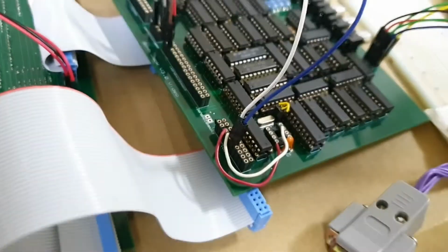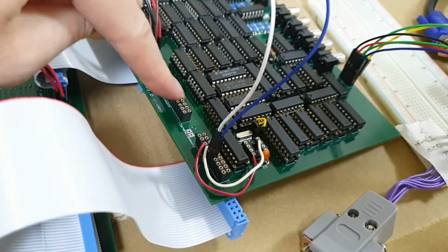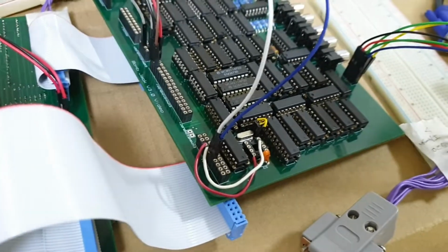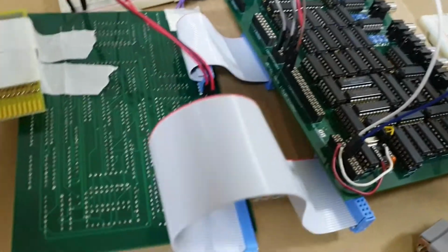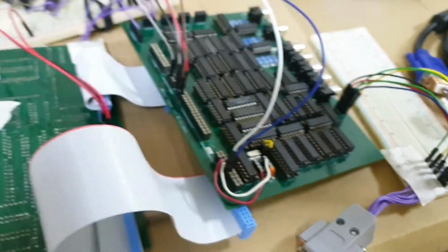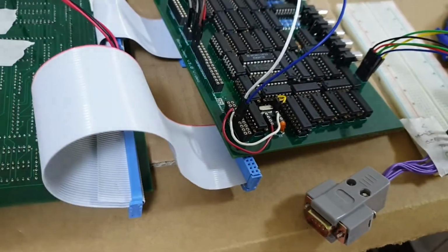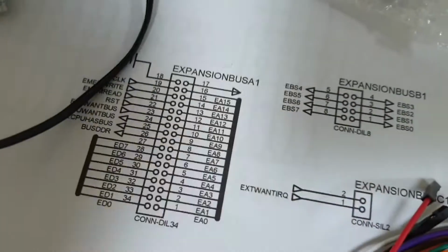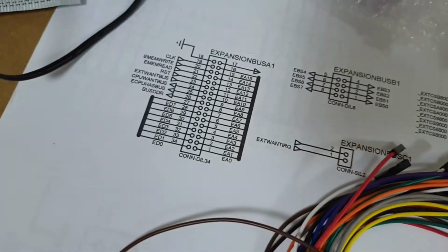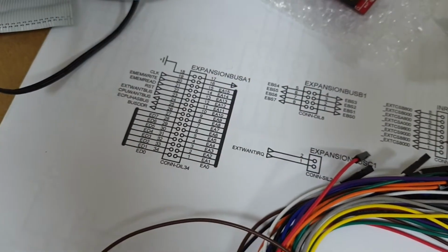And the reason why I like these long pins is that, as a debug thing, I can poke my debug connectors in the top sockets here, in these headers here, but have the board interconnects all connected up via the pins underneath, which is great for debugging purposes, when I debug this board in isolation and connect it up to the logic analyzer. It's very comfortable. So I like this arrangement. As I say, I'm just going to make this cable a lot shorter, and then I will have another 34-way interconnect here as well, just for the memory bus. The 34-way expansion memory bus looks like this, right? This was for the debug. This was for the 6502, 6510, like TTL project I was doing, and the memory bus seems to work really quite well.